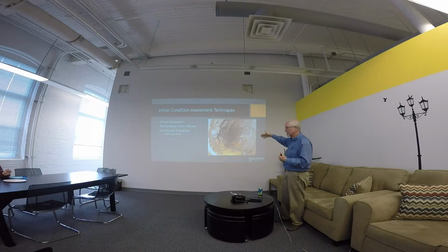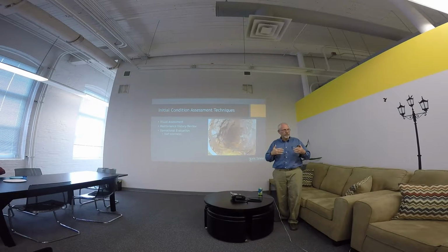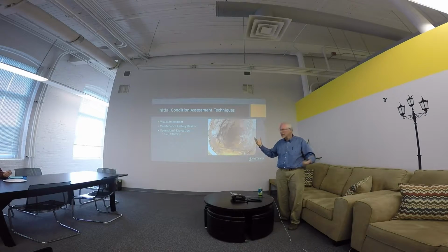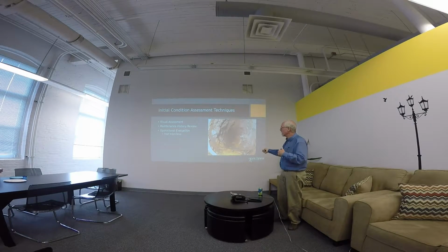Now, is this condition able to be fixed through operation, or does it need to be replaced? Well, through directional flushing, you could actually recover the majority of this pipe size, or through polypigging or something along that line, depending on it. But if this was flushed twice a year, this pipe would probably be a lot cleaner.